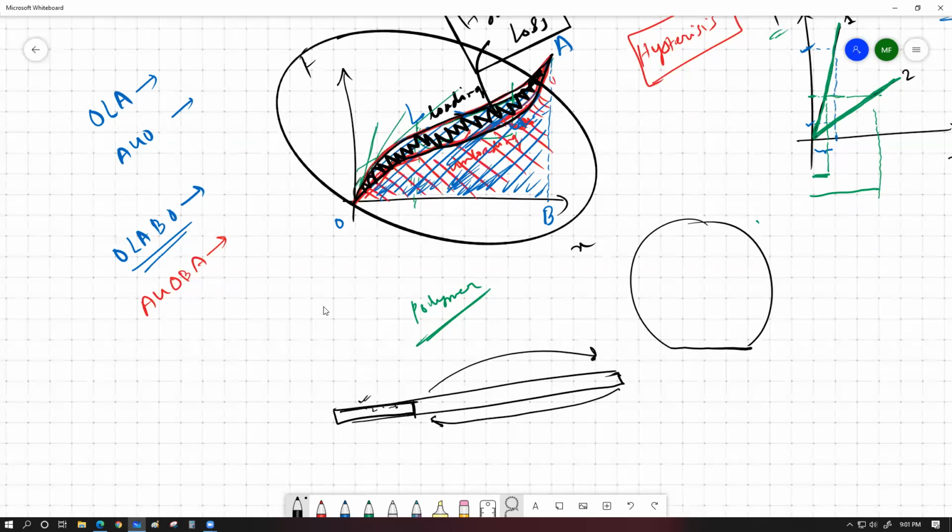because you have to have a situation where the amount of heat energy that we are storing within the specimen for every single cycle of loading and unloading, if we do not allow that heat to dissipate away, then you can slowly accumulate the heat and raise the temperature high enough to make a fire out of it. But if you cannot store the heat within the specimen, if the heat is getting lost by radiation, conduction, or convection, any of the three processes of heat transfer, then you are not going to be able to reach that high temperature. If heat is not lost, you can definitely make a fire. You can make a pretty high temperature. If heat is lost, then no. Understood?